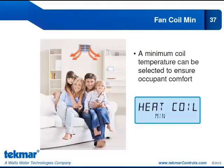Fan coil min is a setting that is also in the 545. So if you're familiar with the 545 thermostat, you're familiar with the fan coil minimum setting. And that is just to set a minimum coil temperature that must be reached before the fan is turned on, so that we avoid blowing cool air into a space. Now, obviously for this, you will need a coil sensor in your application.